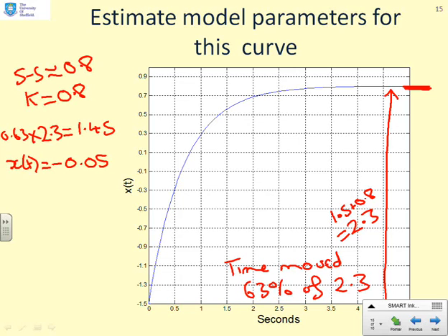So you add 1.45 to minus 1.5, and you get minus 0.05. And so you will see this is about here. So if I take this down, this gives you the value of T, so T is approximately 0.7. I can't really be any more precise than that because I'm estimating from a sketch, and that's why I'm going to use approximation. So your final equation therefore is 0.7 x dot plus x equals 0.8u.